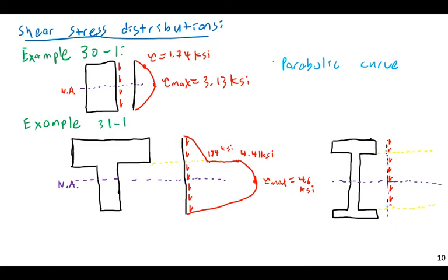So this keeps increasing. Sorry, this is just our shear stress arrows in general. We are going to have a parabolic increase to the web flange interface. Then we're going to have a discontinuity. Then we're going to have another parabolic increase, and the slope here wouldn't be 0. I'm going to purposely draw it without a slope of 0, so maybe something more like that.